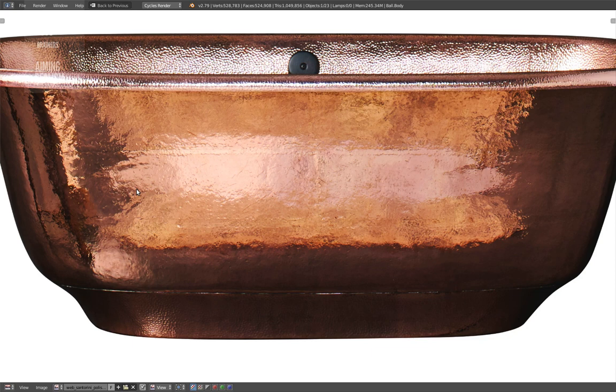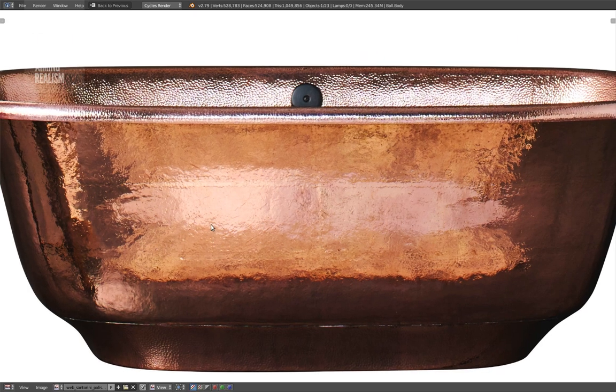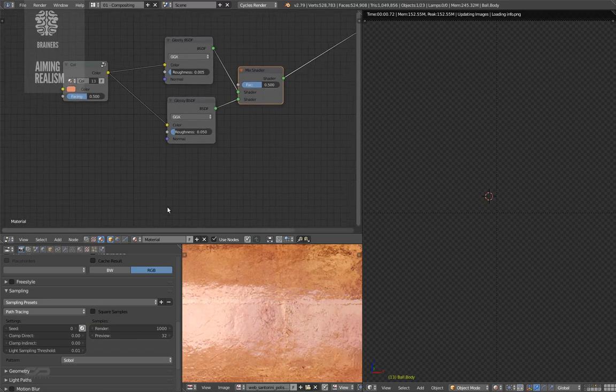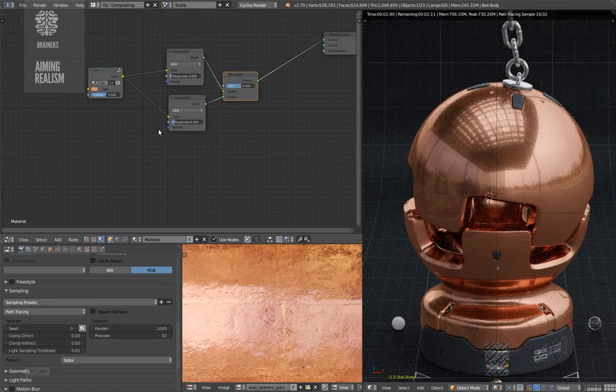So, this machine is pretty slow right now because I have only a GTX 980, but my next machine will have four graphics cards, so I'm not gonna even care about it. It will run at the speed of light. So even if the texture becomes much more complicated, with the power you have it will reduce the render time, and you can trick the texture with the light path node to make it go even faster. So that's why I decided to go with procedural.